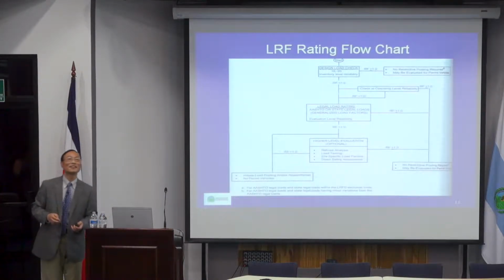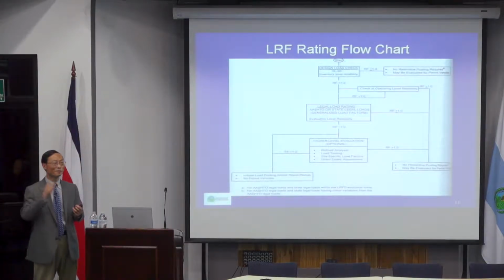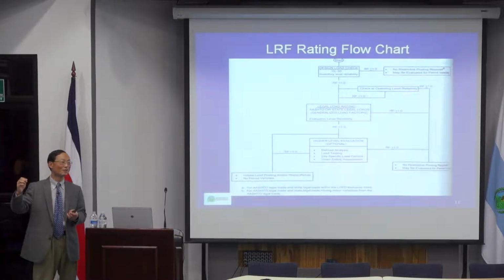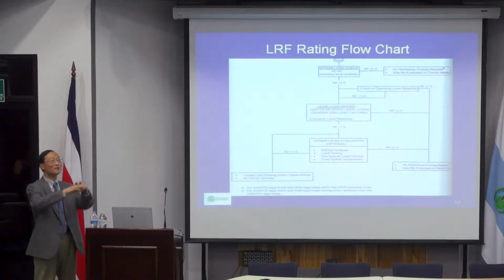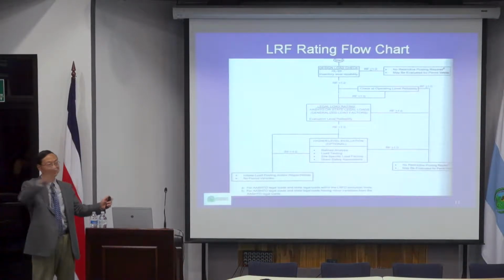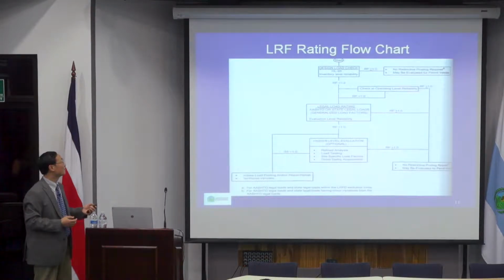Again, in the United States, there's no national standard for infrastructure. It's only regulated by state governments. So each state may have a different legal load, which typically is lower than the design load. The design load has to be an envelope of national standards, so it's always larger and heavier than the legal load. So each state has a legal load, but AASHTO also has a model legal load too, if the state does not have its own legal load.